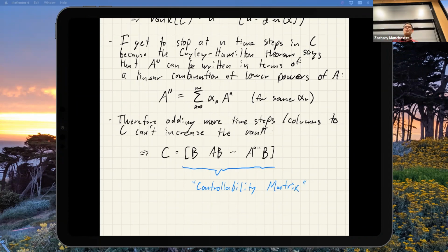Okay, so does anyone have any thoughts on what I do in the time varying case? This is for LTI, where A and B are fixed. How about the linear time varying case? So n here needs to be the same as the number of time steps I have to take in the horizon of the problem I wrote down, which is the state dimension.